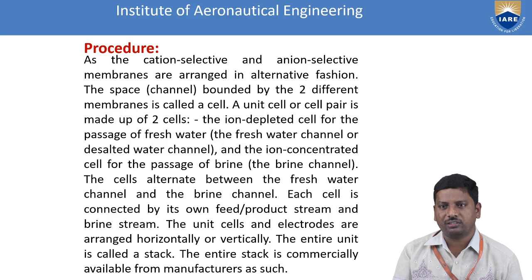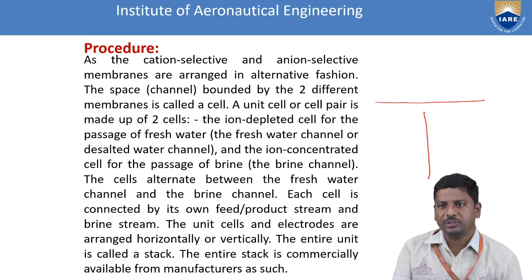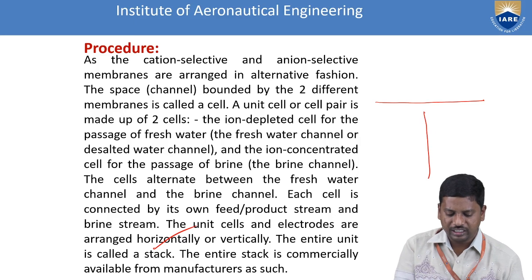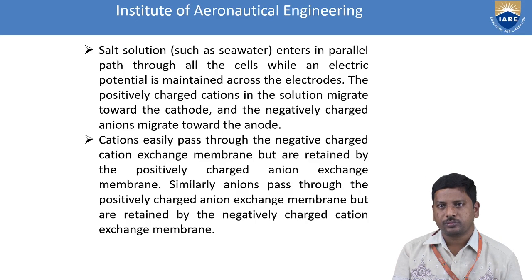The unit cells and the electrodes are arranged horizontally or vertically. Horizontally means the plane lines; vertically means these lines. Because of these arrangements, the entire unit is called a stack. The entire stack is commercially available from manufacturers. The salt solution, the seawater, enters a parallel path through all the cells while an electric potential is maintained across the electrodes. That means the electric potential, the applied EMF, is very important.